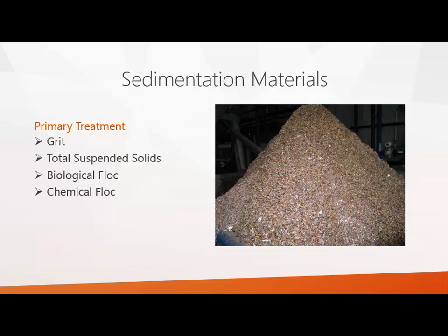And then any flocculants that you got to come out, whether it's biological or chemical, that's going to be mixed into that pile of mess there. You can see some of it's shiny. I would say the bulk of it is grit and sand and little small pieces of glass. Again, it's finer than the stuff you had in the screening. It would kind of be what would come out of the macerator. It's not ground up, but it was just already the smaller particles.